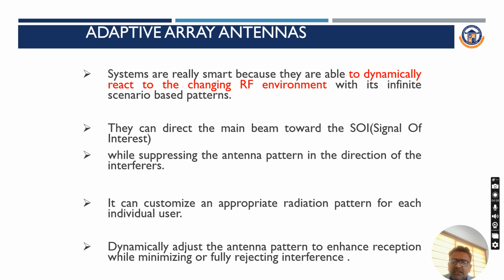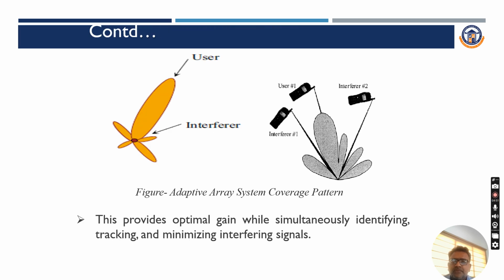It can customize an appropriate radiation pattern for each individual user, dynamically adjusting the antenna pattern to enhance reception while minimizing or fully rejecting the interference. So this provides optimal gain while simultaneously identifying, tracking and minimizing interfering signals.